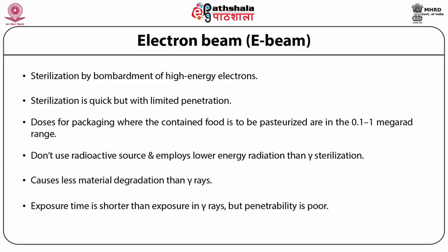Plastic parts sterilized by electron beam are only exposed for minutes versus hours or days with gamma rays. However, the penetration capability of E-beams is poor, resulting in the need for many E-beam sterilized pieces to be irradiated from multiple sites to ensure complete sterilization.